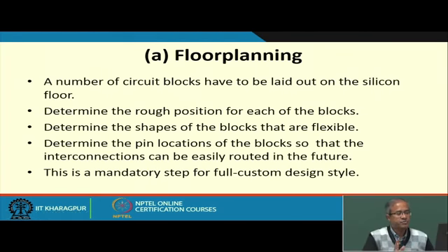Now, again here we are coming to the design style related issues. You think of the semi custom or standard cell based designs where all the cells are placed in rows. So, now my placement problem is not unrestricted, it is not that I can place anything anywhere. A block or a cell I have to place only in one of the rows. Okay. So, the floor planning problem per se does not exist in standard cell designs.